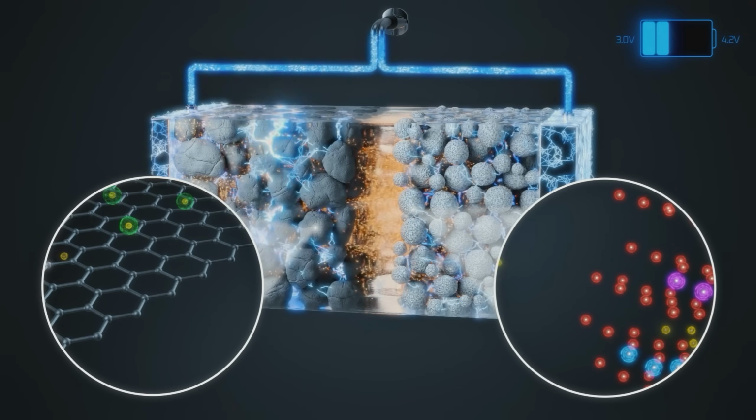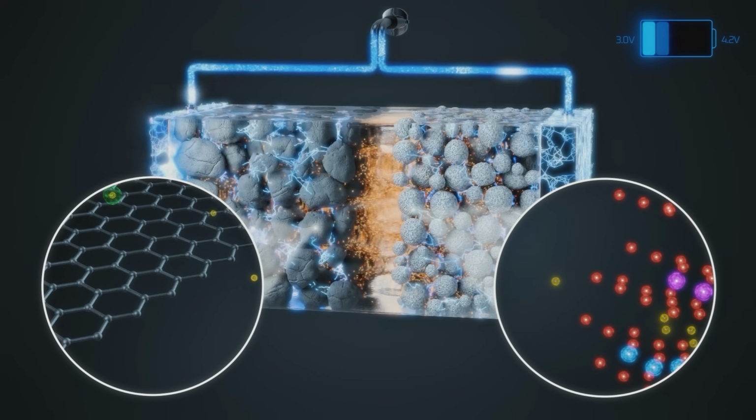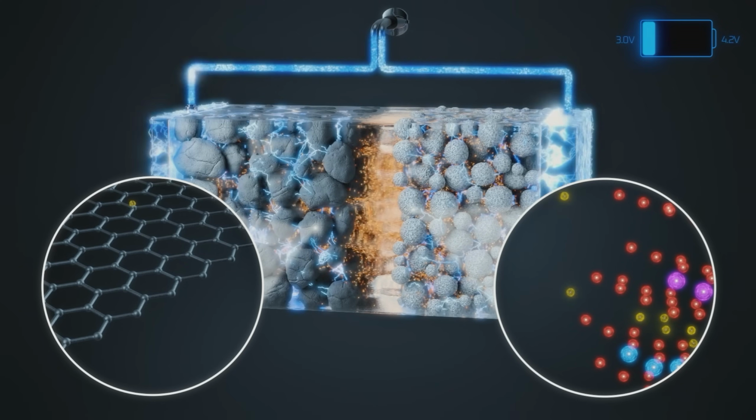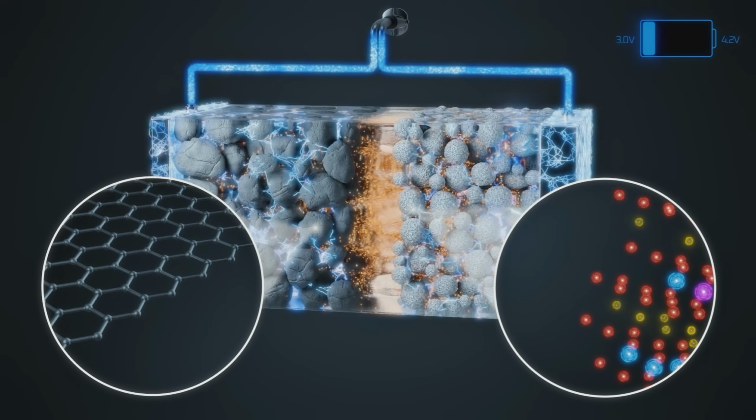And why this works is because in a battery that is degrading very slowly compared to how you're using it second by second, there's a correspondence between the number of electrons going through the external circuit and the number of ions going across the battery internally. And so it's like bookkeeping or accounting. We can basically, indirectly count how many ions are moving across the battery by counting the electrons in the external circuit. In some ways, this is the only way we can measure the state of charge.